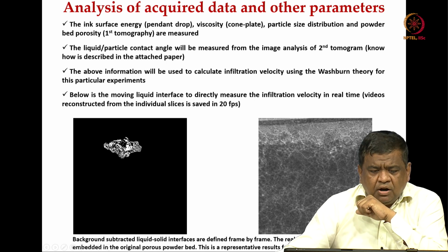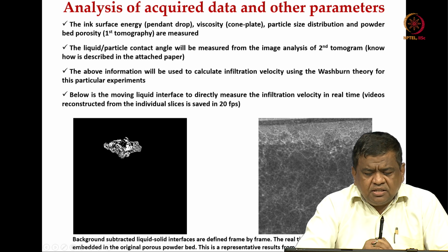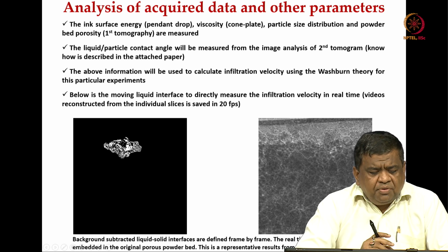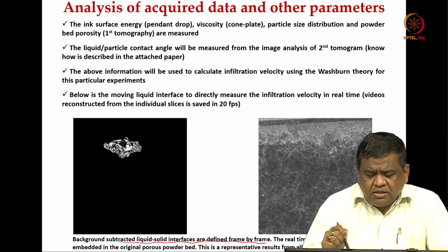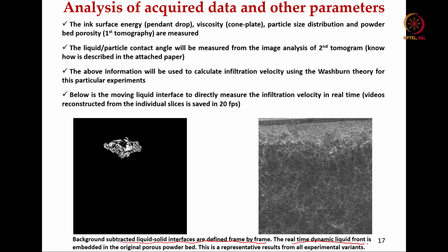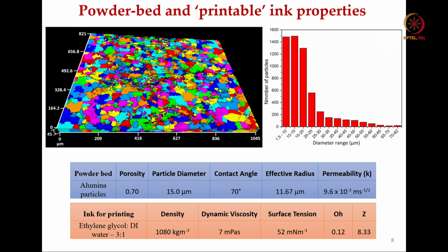So, in this particular slide you see some examples of the acquired data. For example, the first thing is that the background is to be subtracted for the liquid solid interface frame by frame, and the real time dynamic liquid front is embedded in the original porous powder bed. So, this is the porous powder bed as you can see, and I will show you some more examples.